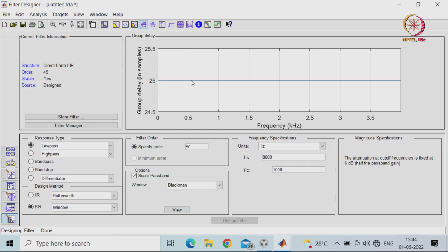So, here the delay is going to be, although I have 0 to 49 samples, I should have had a delay of 50 samples since I have used the linear phase property. That delay, if you remember your structure, comes down by half basically. So, the constant delay of this filter is going to be 25 units. After that you will be getting your output continuously if you are running for real time applications.